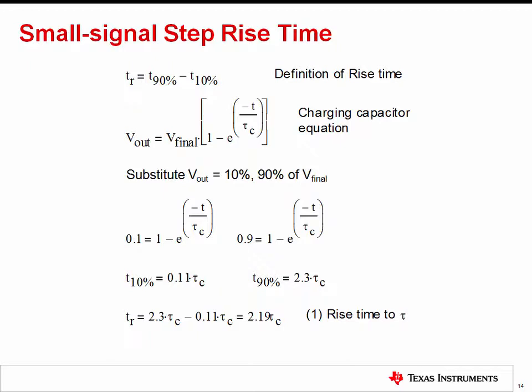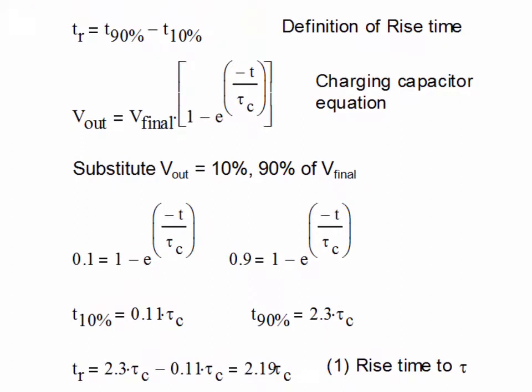Well, as you may remember from the first slew rate video, a large signal input step puts an op-amp in slew limit and therefore forces it outside of its normal linear operation. A small signal step input, on the other hand, allows the op-amp to operate in its linear region, and therefore the rise time is based on the op-amp's bandwidth.